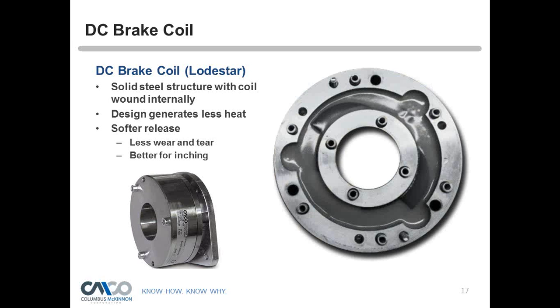And there's the bottom portion of it. Now, the reason I show this picture here is you're wondering, where are the springs? So we had the brake field, right? And you can see these right here. These are the individual springs. In this case, you have many springs that apply the pressure to the friction disc, which you can't see. It's covered, but there'll be a plate that sits on the friction disc inside here, and when this field is magnetized, it'll pull that plate up and allow the friction disc to spin free.